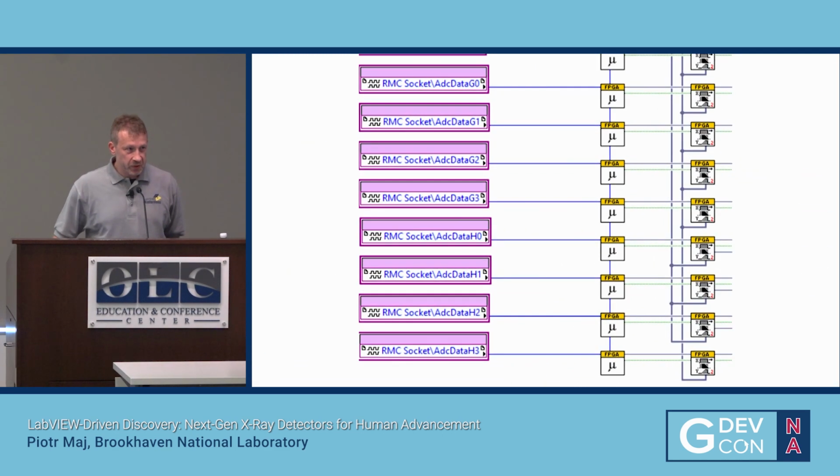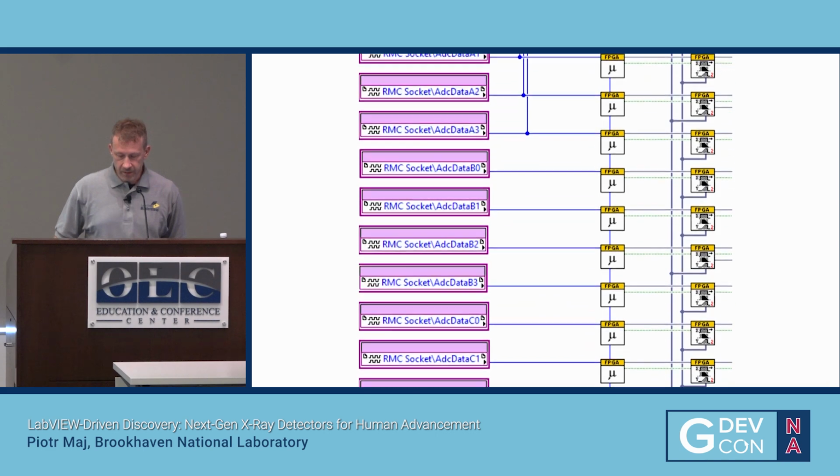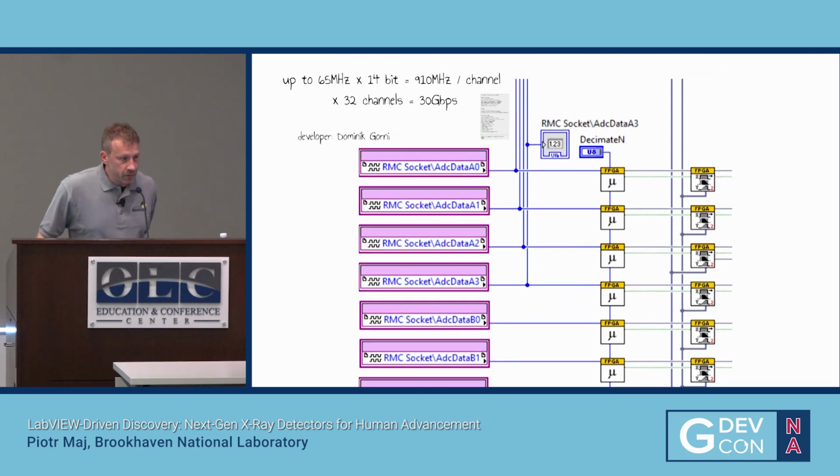I know you're interested in just a glimpse of code, so maybe I will show you one example. This is a piece of FPGA code. It has 32 channels, so it goes like up and up and up. And we connected 2 analog devices ADCs, 14 bits, up to 65 megahertz. I will just read this for a second so you can read the numbers. Our FPGA code can change this frequency fluently during the operation up to 65 megahertz.